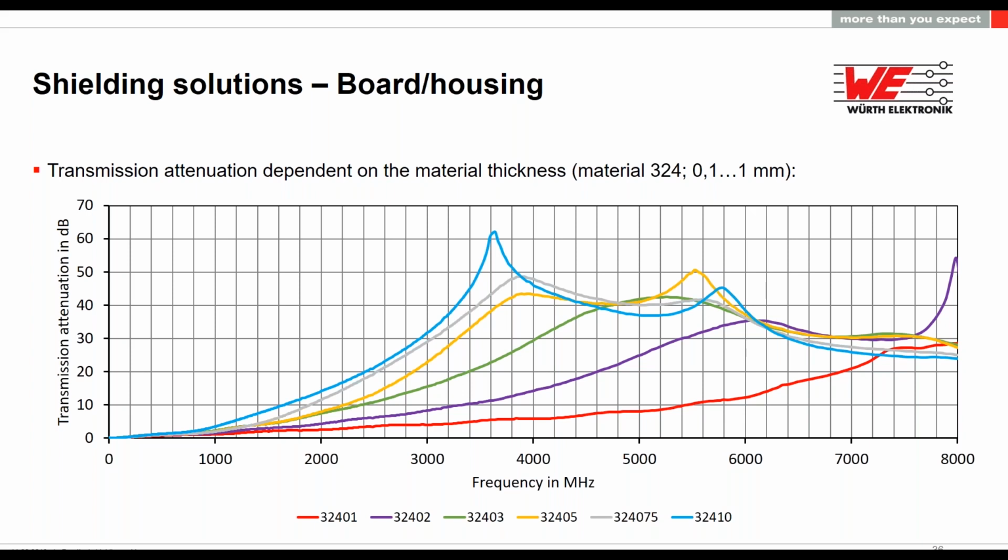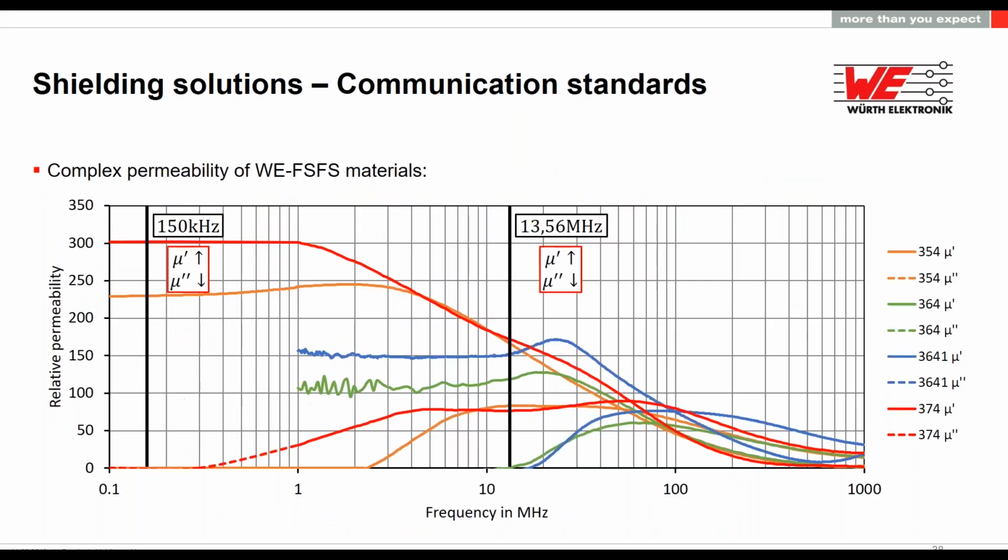But if you want to use shielding materials on the side to erase these kinds of problems, then you have to go again to the permeability values of the material. If we have this core on a coil that is working at, let's say, 1 mega, it's important to have a material that has reflection or absorption capabilities in the frequencies you want.